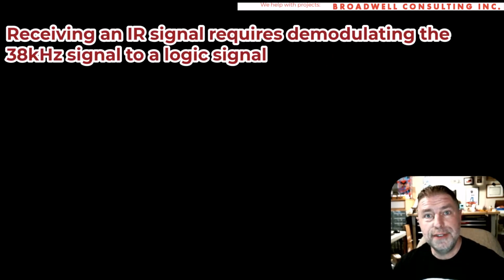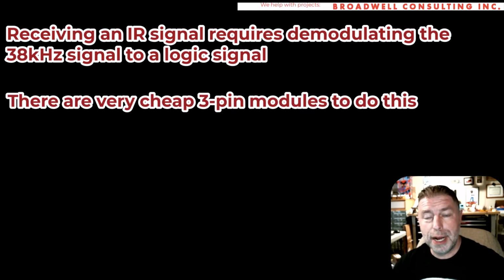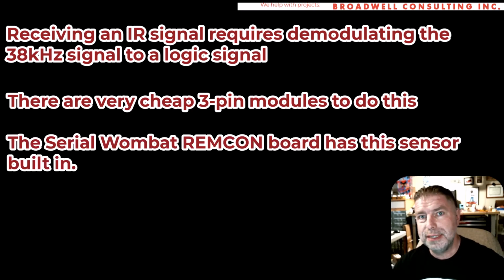In order to receive and decode IR remote control signals, a demodulator is necessary. This is almost always an external circuit or module and is frequently included in the 37 sensor kit packs that you get, and is readily available from a variety of sources. Again, you need to choose a demodulator for NEC protocol that uses 38 kilohertz specifically.